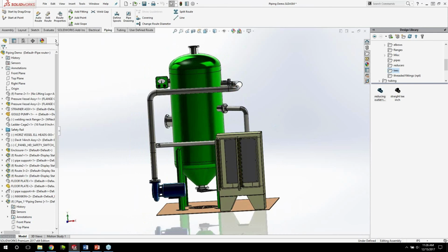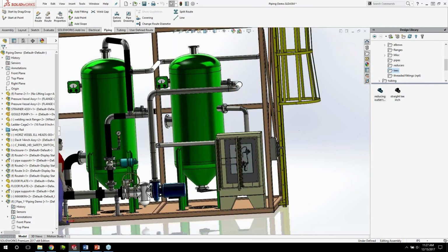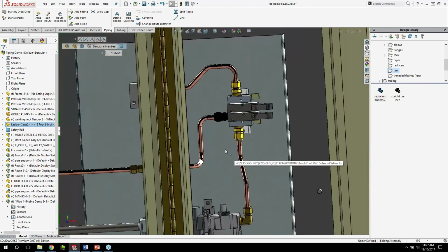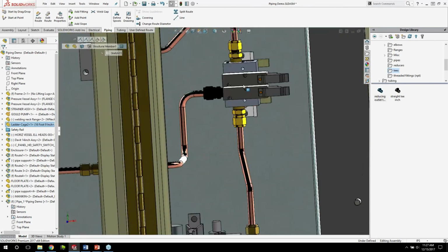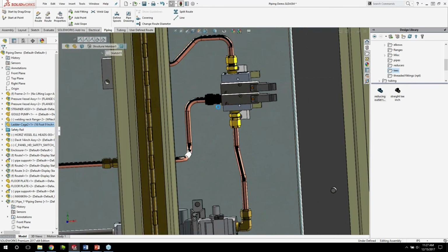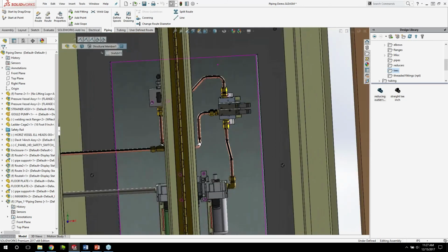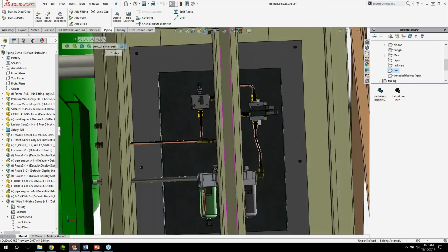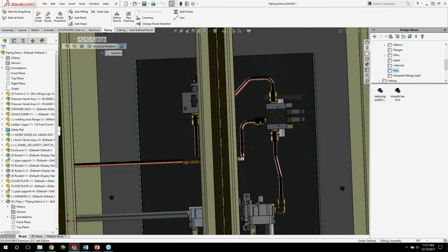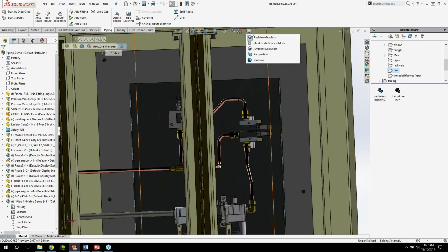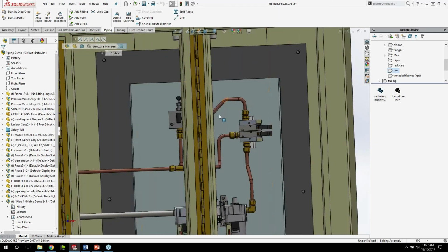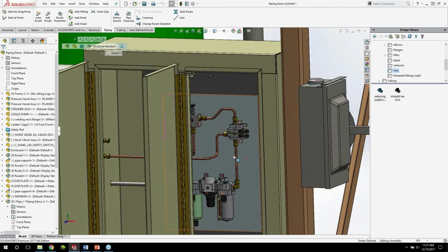Right. So you can do that with the rigid pipes and tubing, flexible tubing as well. You can see some of those examples here. Works the exact same way as kind of everything we've seen already here, right? So you'll have these fittings. You say connect from here to here, auto route it. And if you need to manually create that sketch to show how you're going to be creating that tube to suit your needs, you can go ahead and do that as well manually with 3D sketching.